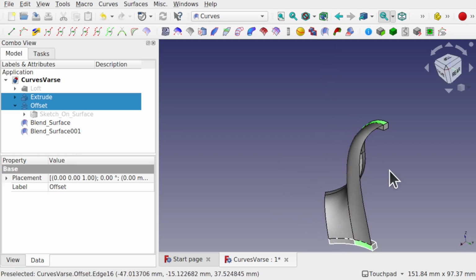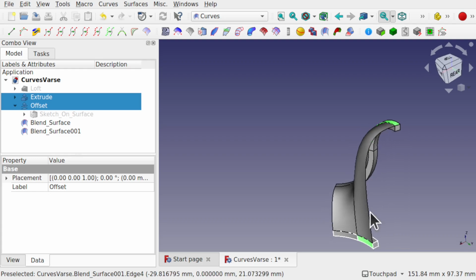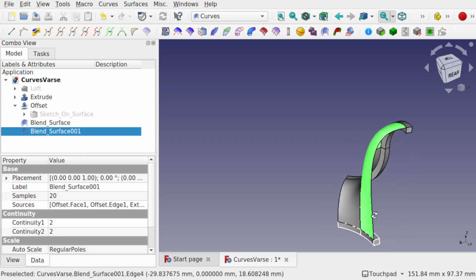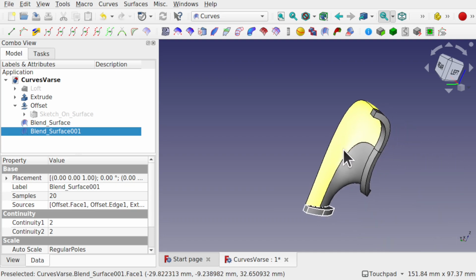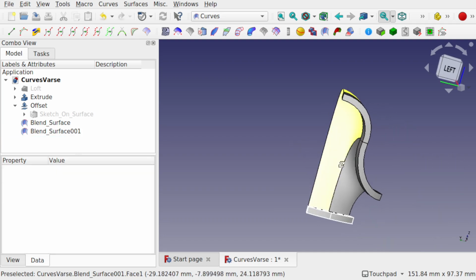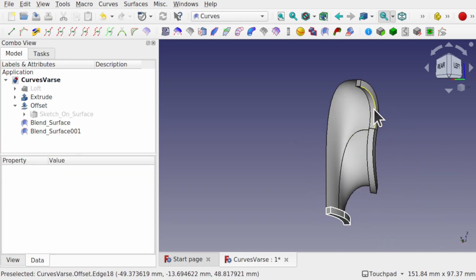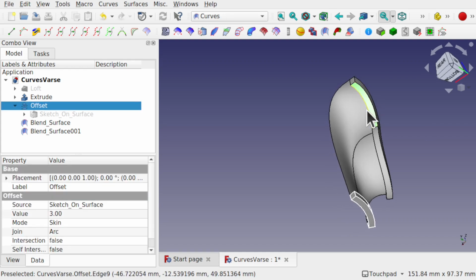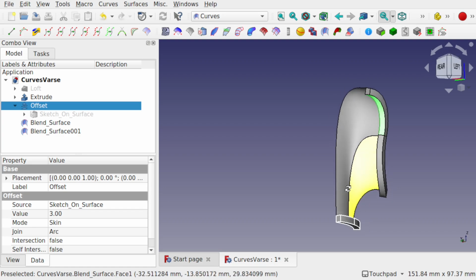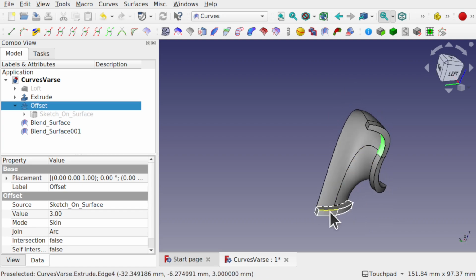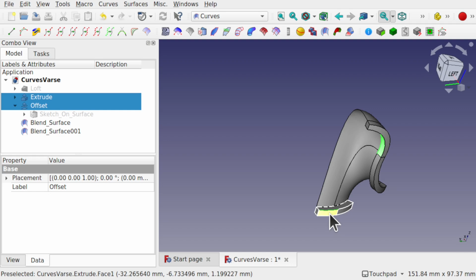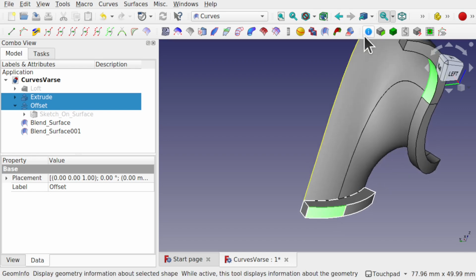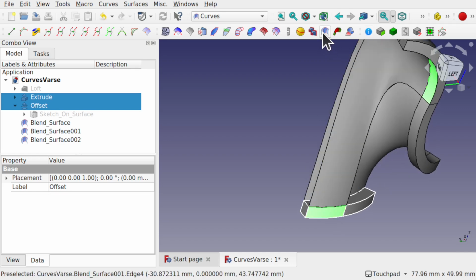Now we've got the back down. Let's have a look at the front. Come around to this side and we do the same. Looking here, we've got the surface, control click the edge, and come down, control click the edge, and click the surface, and use the blend tool.